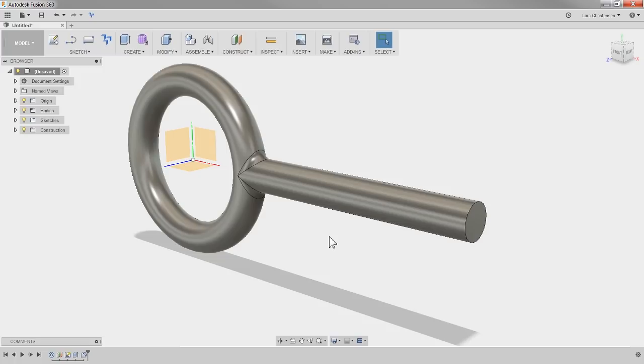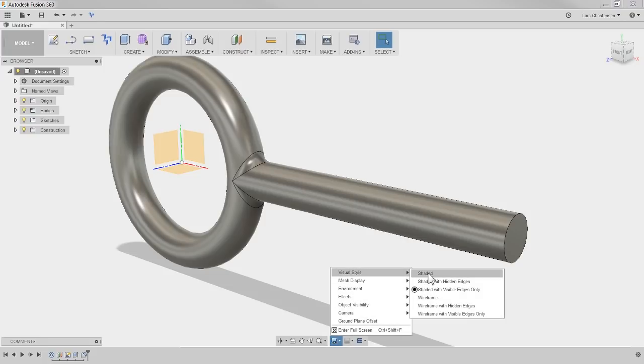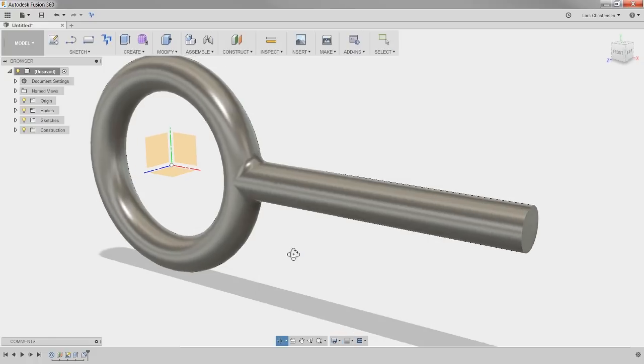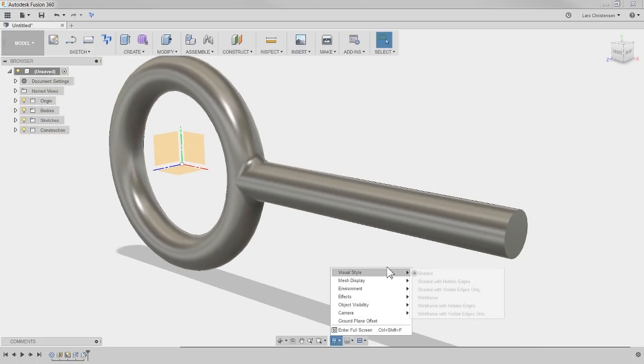But if we're making a 3mm fillet, that might look pretty good. And hit enter. Now notice that the fillet might look a little strange because you have those visible edges on. It makes modeling in CAD a little bit easier, but remember, in real life, if we went back to the display options and turned it from visible edges only to just shaded, that would look a little bit more real. But most people when they are actually modeling in CAD will have shaded with visible edges on, so we can see it here.